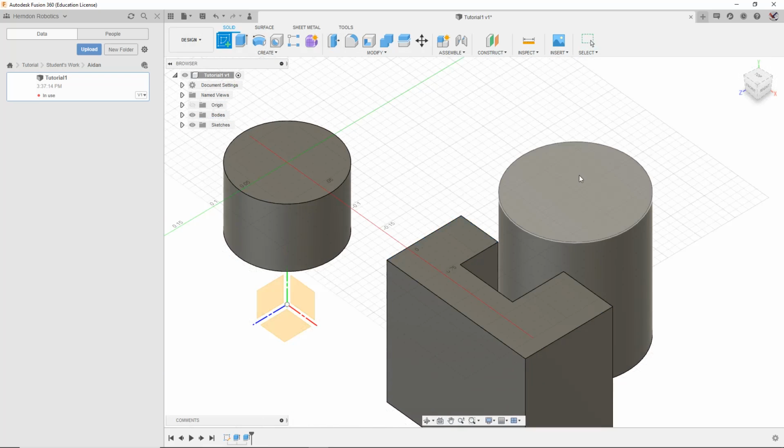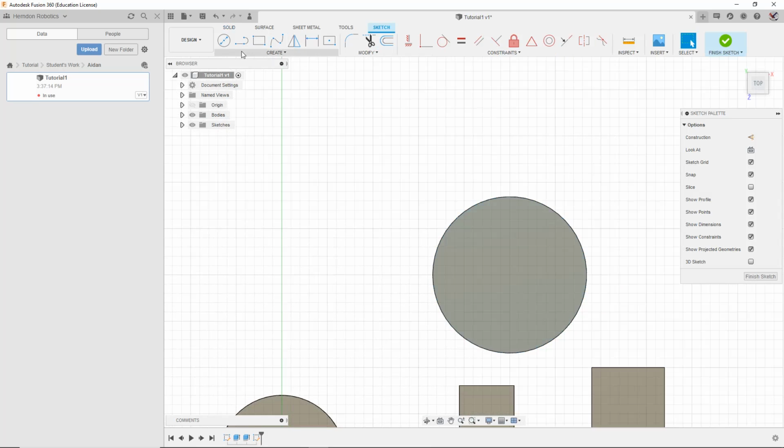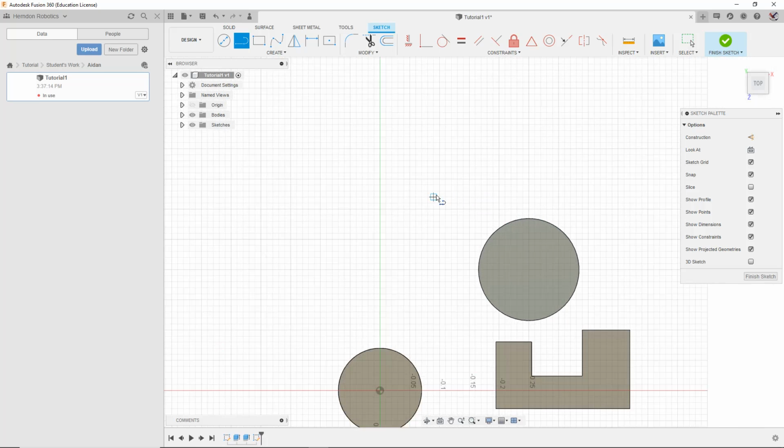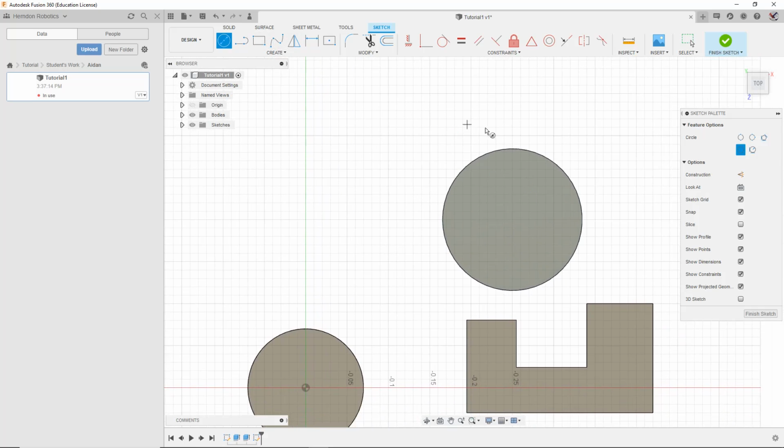So I can come here, click on this face to create a sketch here, and you may say, well, why don't I just extrude it? But let's say you need to make some modifications. Let's say this person has an iris because they're human. Well, first off, we need to find the center of the circle, and that can always be a bit difficult.